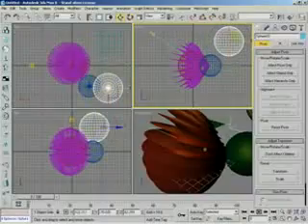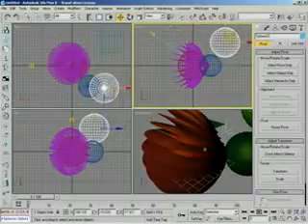And when I was moving, you could technically say the same thing. Where was I moving the object from? From its center. It's kind of the point where 3ds Max is grabbing the object and transforming it. It's where it's calculating those transforms. Now, in this particular case, where is our pivot point for the object? Dead center. Bill, can we affect that pivot point location? We sure can. And we do it from this panel right here.